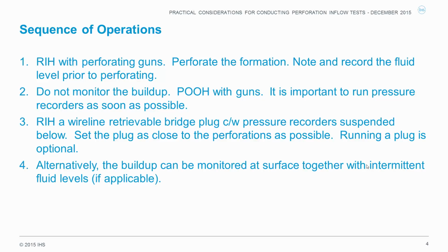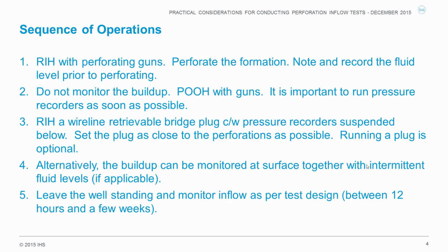Alternatively, the buildup can be monitored at surface, and if there's a liquid level present in the wellbore, intermittent fluid levels should be taken. Leave the well standing as per the test design, and finally pull the bridge plug with recorders out of hole on the final day. So the procedure is fairly simple. Perforate the formation and monitor the pressure response.